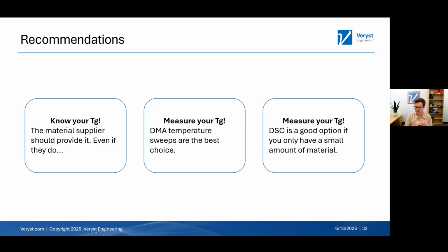The other way of answering is what temperatures are relevant. With something like a time temperature superposition test, it really doesn't cost us much to add additional temperatures. We pick an upper limit temperature, and then if we find out later that data is not useful for TTS, we discard that data. So it's typically easier to generate the data first and discard it later than to run the test and go back at the end and say, oh shoot, we should have done another 30 degrees or something like that. So that's typically what we'll do in those cases.